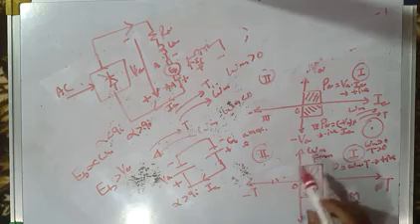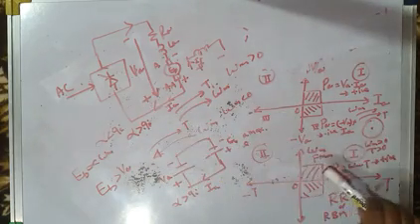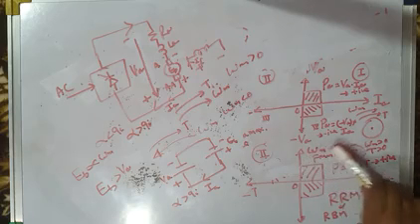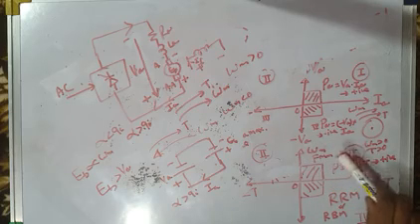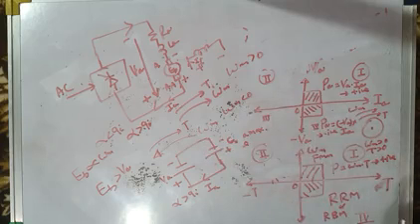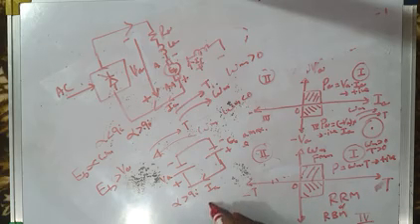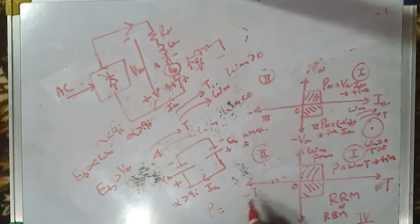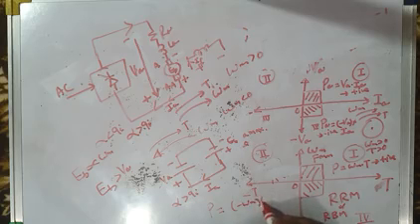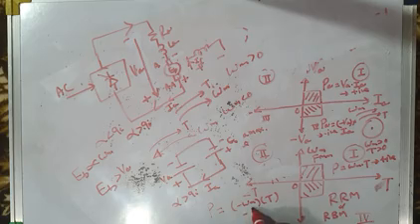Okay, so when the crane was moving up, our drive was operating in the first quadrant, forward motoring mode. And when the crane comes down, our drive is operating in the fourth quadrant, reverse regeneration mode. In the reverse regeneration mode, power is omega into T. Omega has now become negative, so it is minus omega m. Torque is still positive, so power is negative.